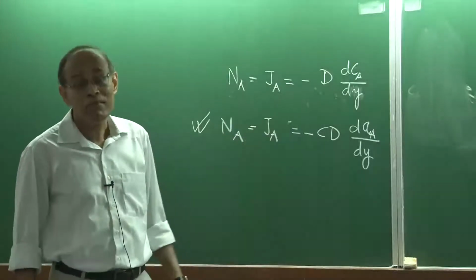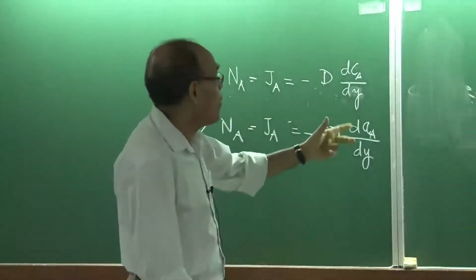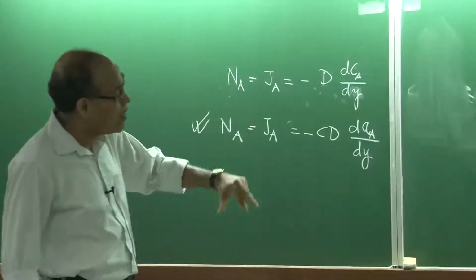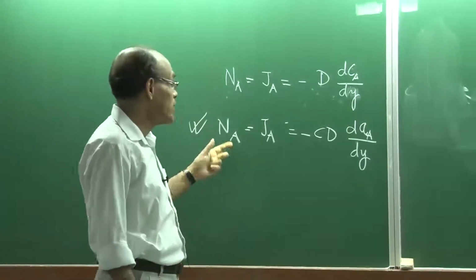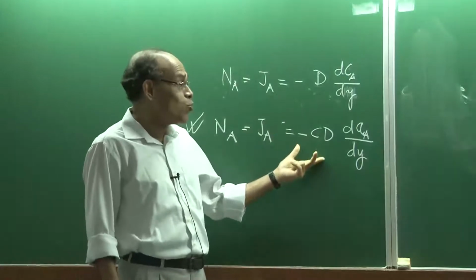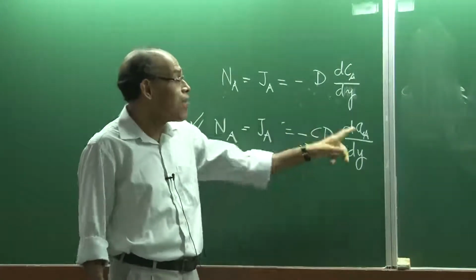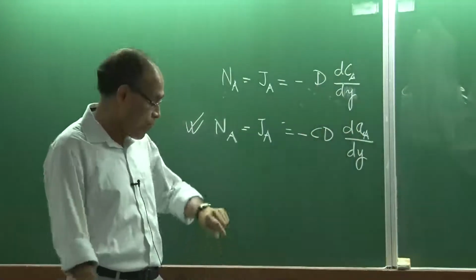But if you are to deal with a system where there are alloying elements which can dampen or enhance the activity of the other solute elements, perhaps it is desirable to formulate Fick's law in terms of activity rather than in terms of concentration.